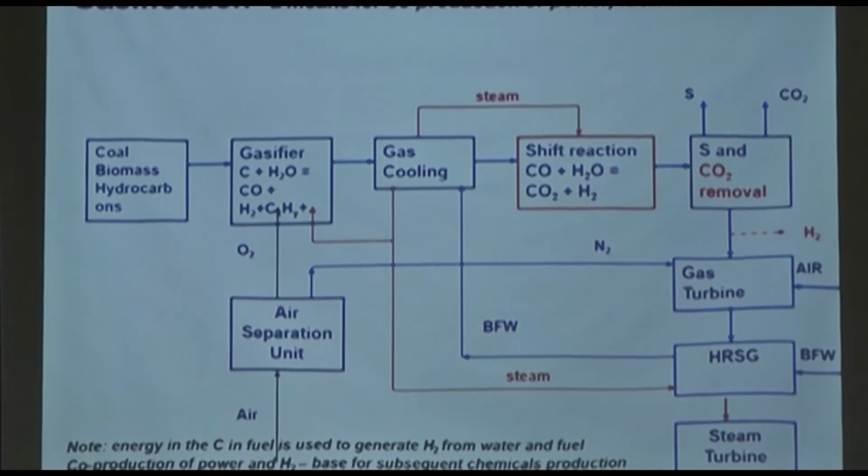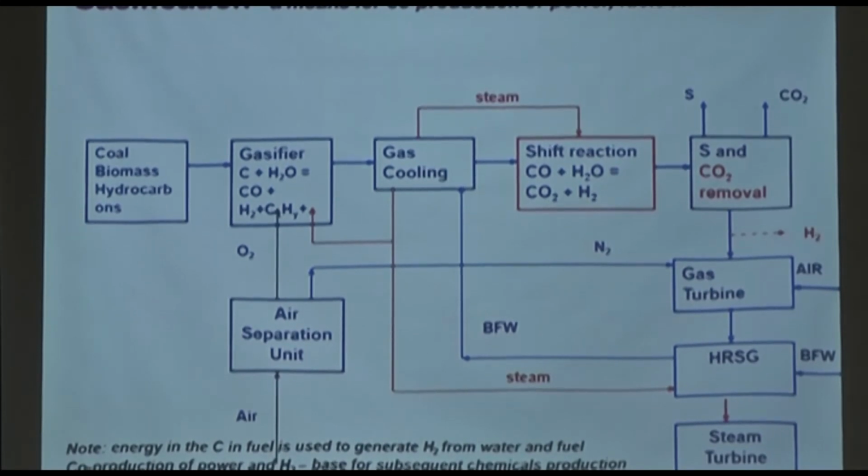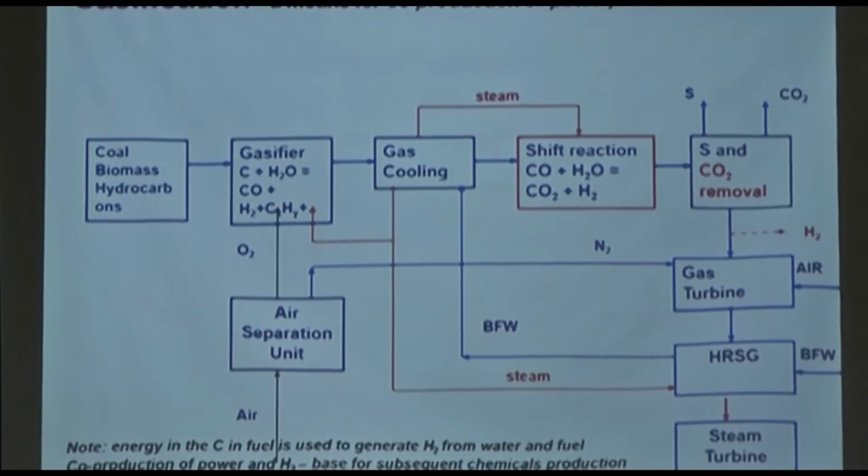We will come to that, but without going into too much of it for the time being, it gives you a combustible gas, which then sometimes is cooled if you want to change the proportion of carbon monoxide and hydrogen. Then you use what we call a shift reactor, which means shifting the composition of the gas.